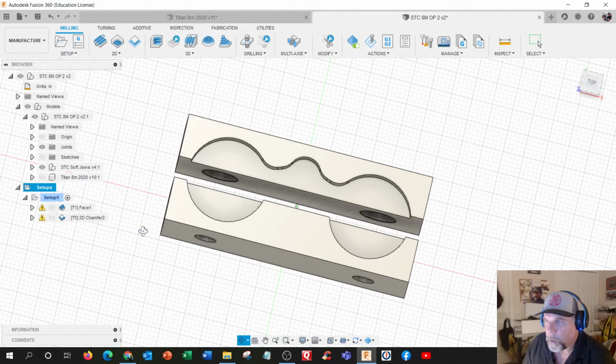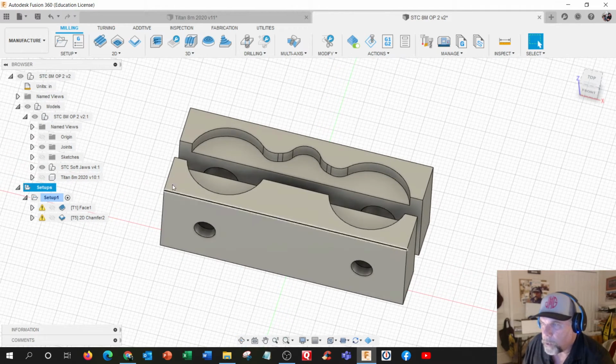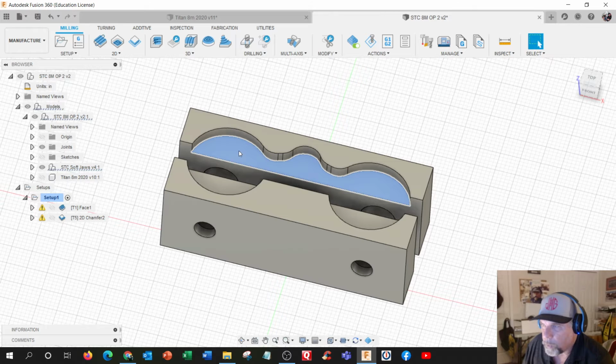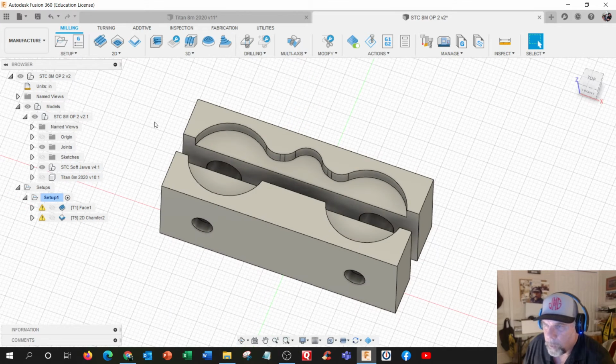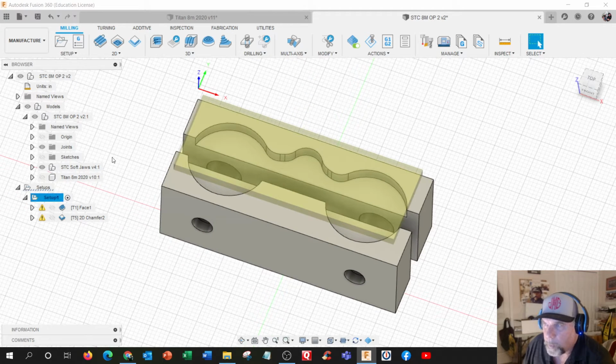So I believe what we're going to do is we're going to go off the corner of the jaw as our 0. And because we'll know where this is, we know how to get to the shape. The Z surface will be based on this surface here, and we'll have to shift it up by the thickness of the part, which I believe is 750. And we're going to use this corner here for our reference. We're going to use this corner for X0, Y0. So our setup,